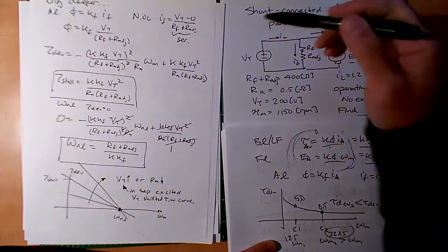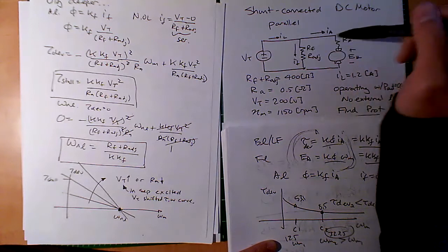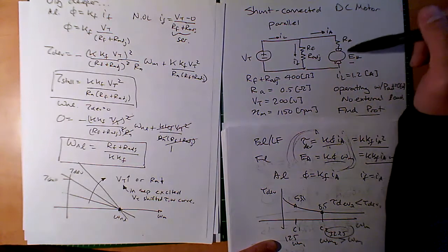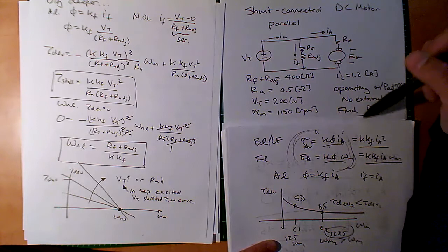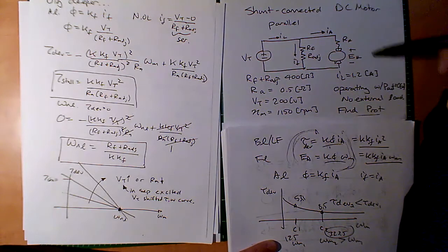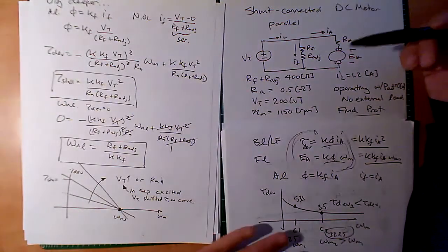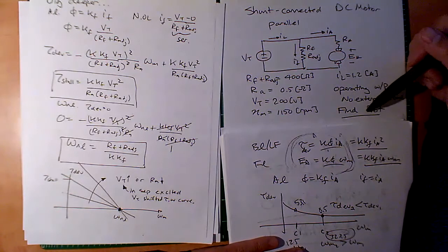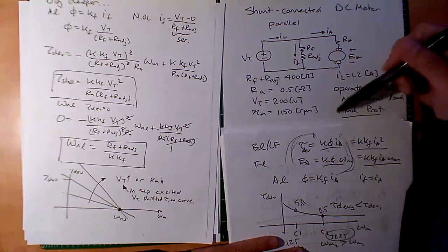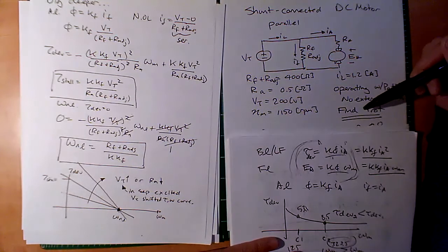Because you can imagine what's happening is you're applying some voltage, the energy is being burned off as heat, and it's being burned off in friction in the bearings, but it's not going into any output power. So it's just like the motor is running without spinning anything. So no load. The question is, how much energy is being burned off just in the bearings and the friction and the windage and all that stuff?